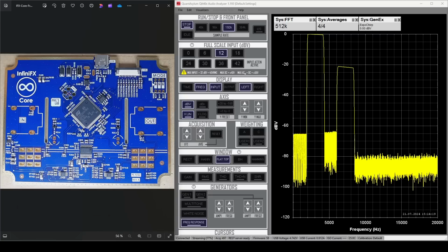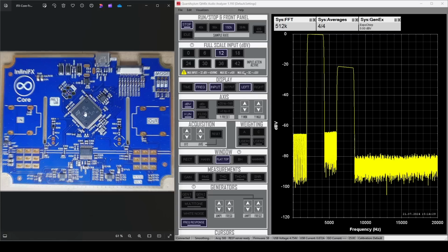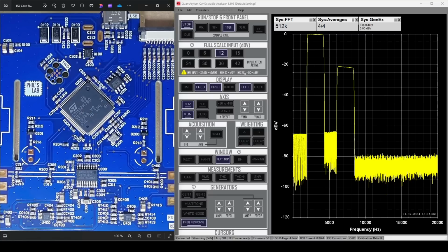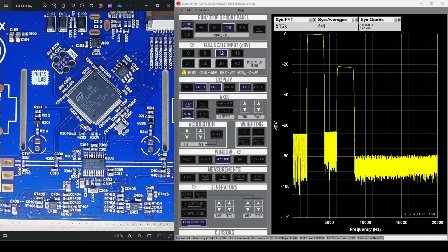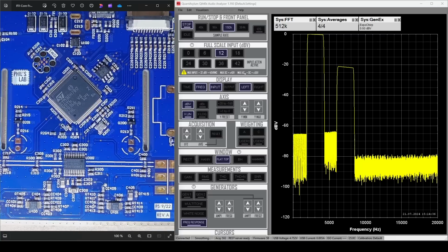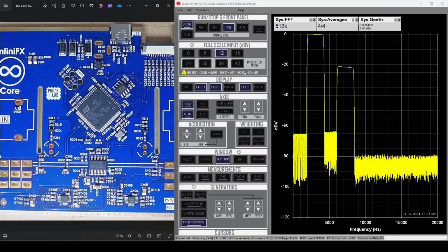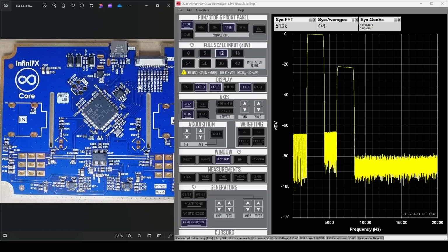What you're currently seeing here is the left PCB, which is a digital signal processing PCB that's featured a few times on this channel. Essentially, it's a single input, single output digital guitar effects processor. At the center of this is an STM32 microcontroller. We have an audio codec, so DACs and ADCs, and analog front ends. And this is just running in mono with USB connections and connections to ADCs for example, peripheral controls such as potentiometers, switches, and so on.